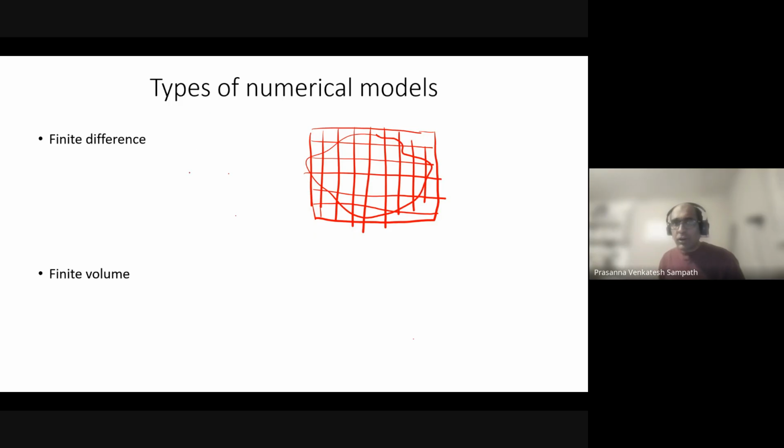This process is called discretization. Okay, why do you think it's called that? Because I'm breaking up this domain into discrete boxes. And what is my final objective? My final objective is to predict inside each box. I'll just draw some random box. This box, I want to know what is the hydraulic head. What is the head in that particular box?